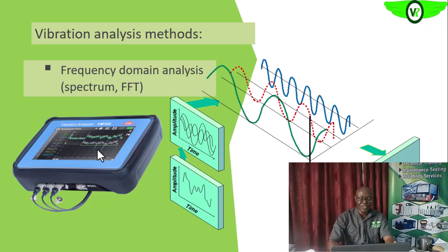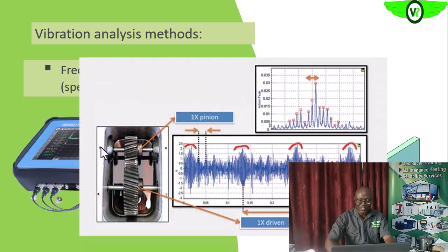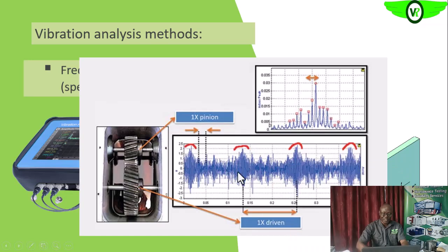But for detailed information, you have to dump whatever information you gather, so that you can compare all the points on a particular machine and then see what is actually wrong with the machine. This is the waveform, and you see how complex it is from this gearbox. After fast Fourier transformation, you have the forcing functions separated into their individual frequencies. The major peak is occurring here.